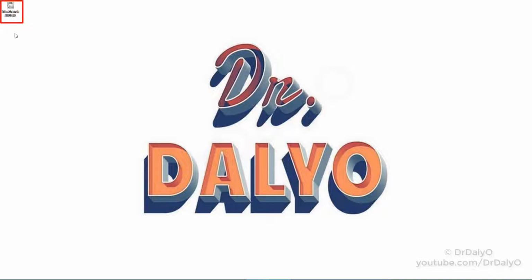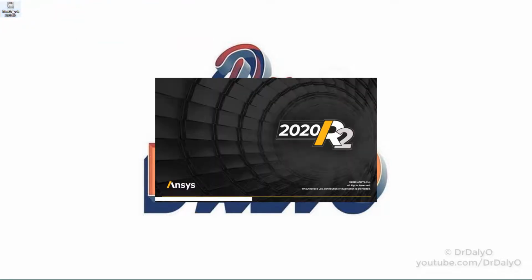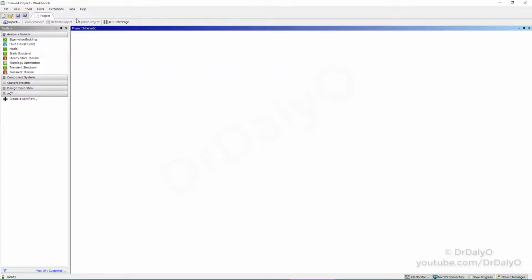Start by double-clicking on the Workbench 2020 R2 shortcut, also titled Run WB2.exe. Once inside Workbench, let's go ahead and click on the units and make sure that the units are set to metric kilogram millimeters. Next, let's drop a static structural from the analysis system into the project schematic. You can rename this to whatever you want, however, I'm going to leave this as static structural for now.